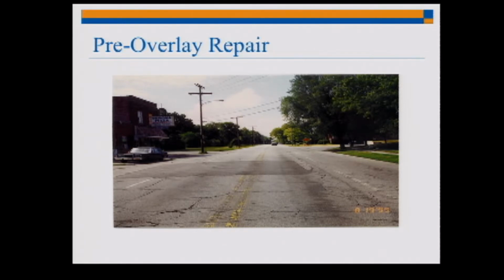So when you design concrete pavements, most people think they last forever, but thin overlays are not going to last 30 years generally. Just like you don't design an asphalt overlay to last 30 years, you're not going to design a concrete overlay that's very thin to last 30 years.